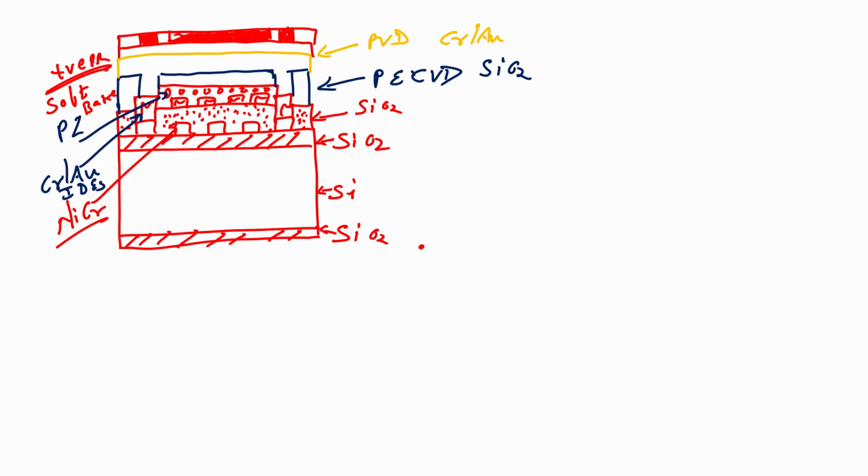So, the region which is dark here, right, because there is a positive photoresist, this region will not expose the wafer with UV. So, if I use UV here for exposing the wafer, you can see that the dark area will not be exposed and the gold below the dark area will be protected.